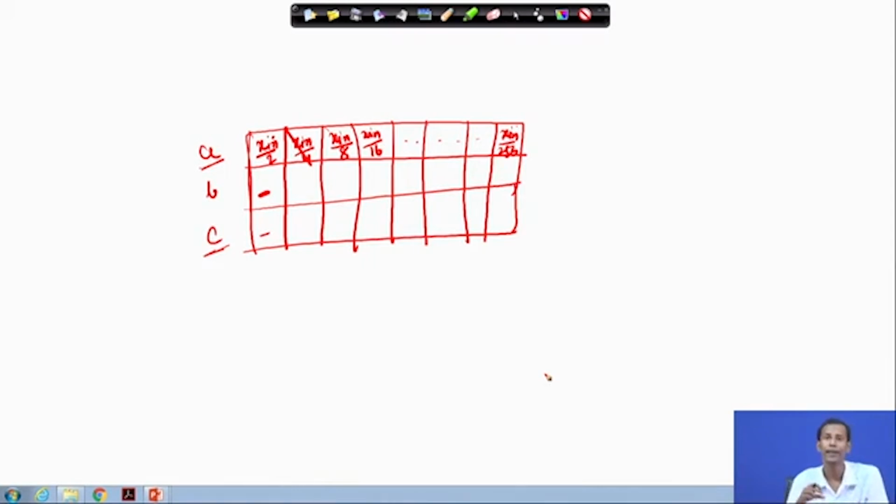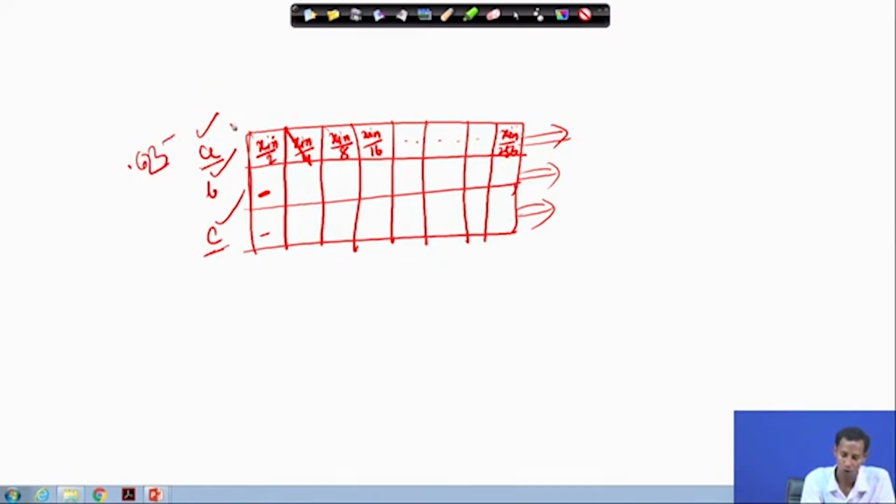Now, if I know A, B, C from the beginning, then each of these multiplication operations will be optimized as in the previous case. If this value is 0.625, only x_in by 2 plus x_in by 8 I have to add to do this 0.625 into x_in.